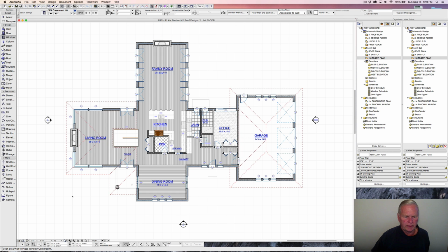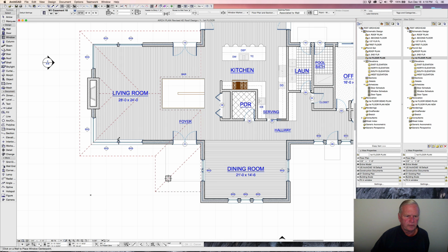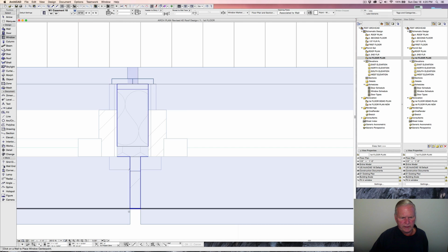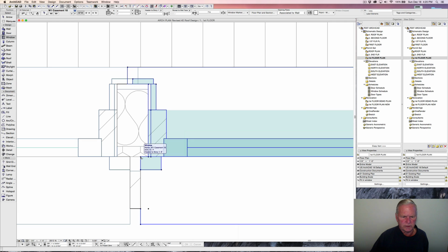And at the floor plan, what we're going to do is suck up the settings for this corner window and place them into the corner window in the back, and that makes its changes. And this picture window, I'm going to suck up those and inject them into the one in back. And then here, what I want is 7 5/8 inches between my brick molds, because I want to have a stack bond course that's going to run in between there.